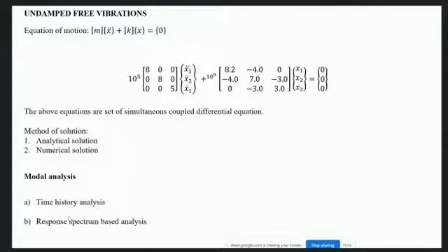And then the other codes which you will require in your future related to earthquake engineering are IS 4326 and IS 13920. These are the codes which talk about some problems which are not mathematical, but they talk about the detailing of the structure so that the structure can behave in a more ductile manner rather than a brittle manner.